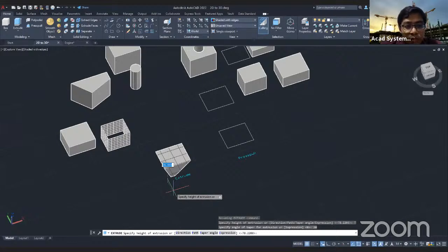Now, to do this properly, all you need is one single face, which needs to be a polyline or spline that is joined, and then the other line will be the axis of rotation. You don't need to combine them together, so it can still be separate.